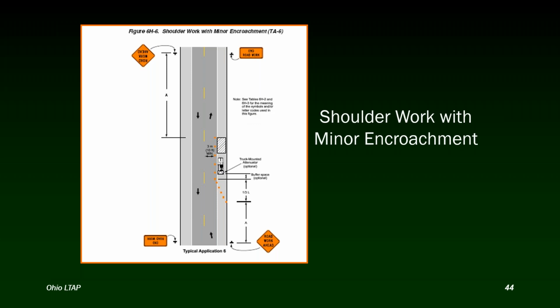If maybe it's a more minor road, and it's off peak or whatever, or even if it's not off peak, some minor roads, then you can close the lane and either consider a flagging operation or just put out the signs. There's a typical application number 11 that deals with low volume roads where you set it up in a way where you don't even need flaggers. The motorists can figure out themselves if they can go around you or have to wait on another vehicle.